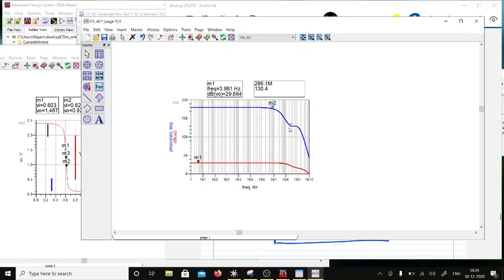Then there would be a roll off of 90. So wherever the roll off has taken 90, this is 180, and this becomes 90 somewhere, right? And before that, this has become plus 90 here, which means that a 0 came in to correct.